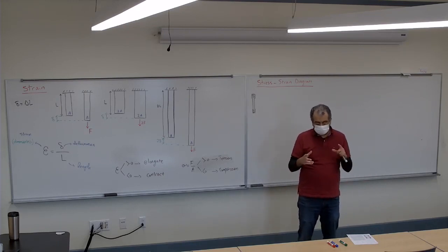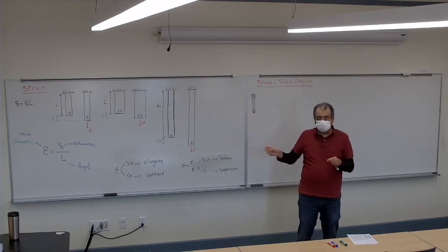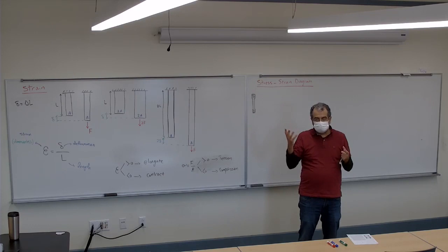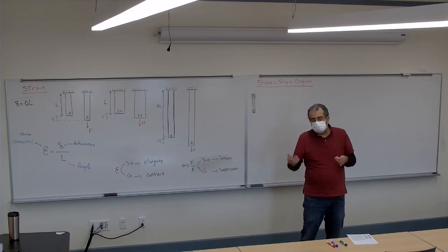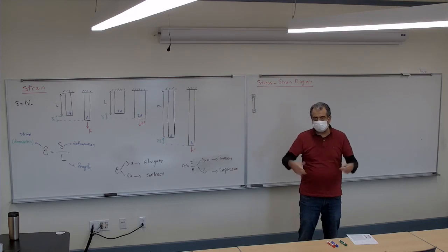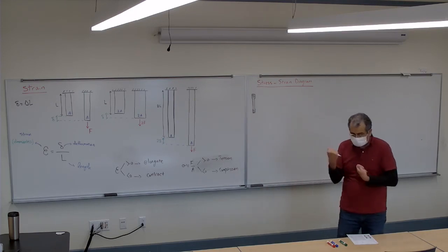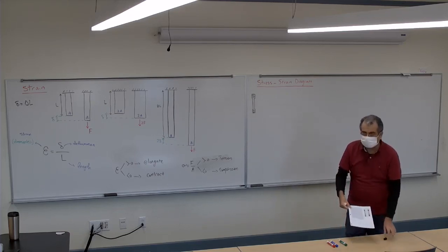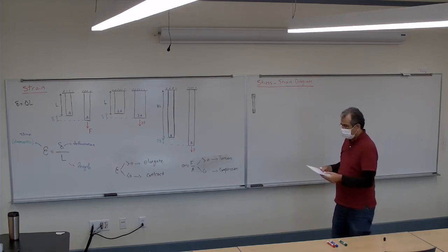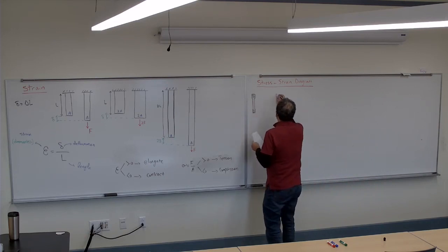Depending on the material, if you run that test 10 times, you get 10 different curves. For some materials, those 10 curves are very close to each other, very similar, like steel. For other materials, you might test 10 times and get completely different results. So steel, because it's very consistent, is the one referred to a lot.